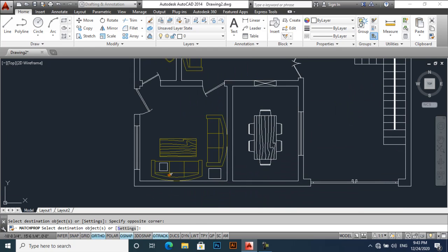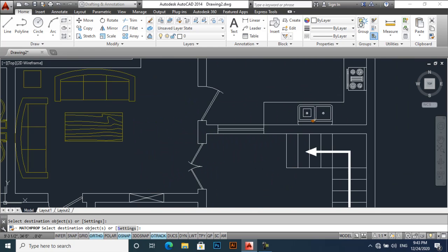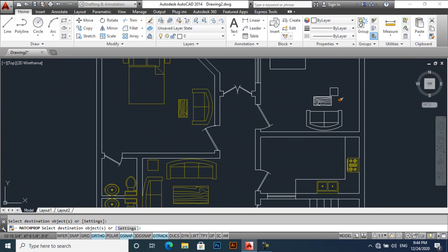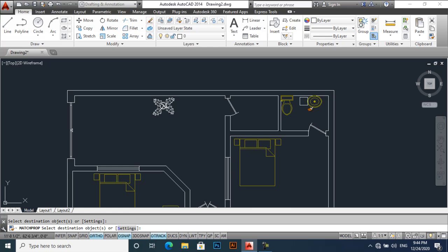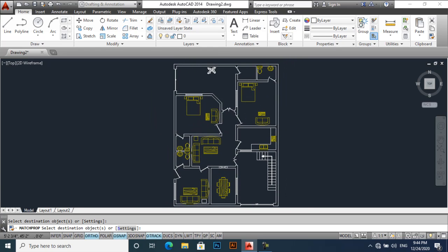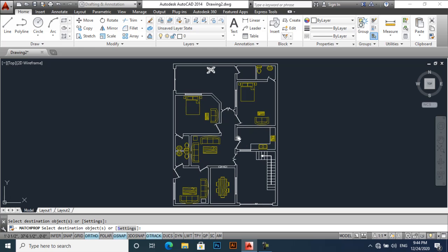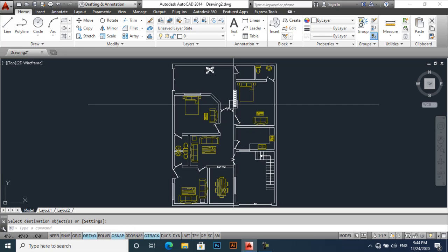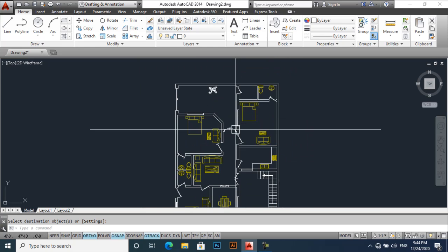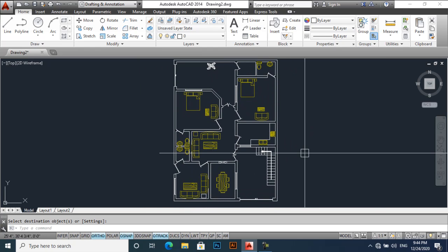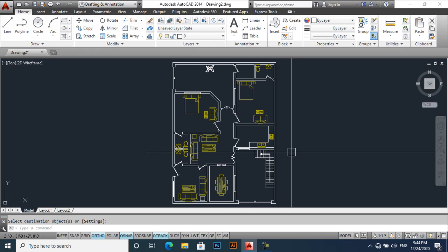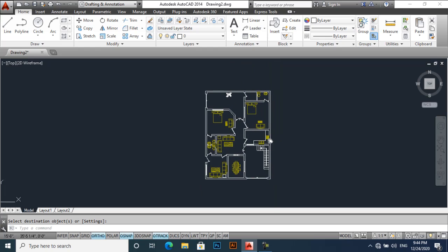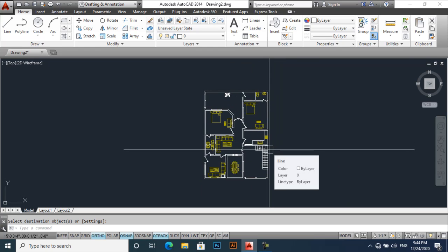You can apply different colors. For highlighting I use this color. Now you apply different colors on windows, doors, and walls, and you also can apply dimensions, and you also can make or create a new layer for dimensions and give it a color, so your drawing will have a good look. This is what you call a ground floor.